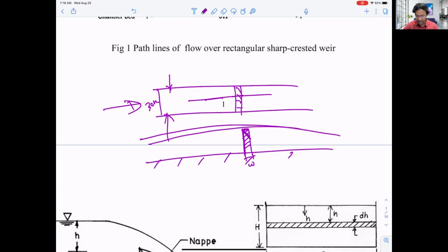How can we measure that? See, if water flows right over this, and if we can measure only this height above the weir, then we can calculate the actual discharge or flow rate. So that is our main purpose. It is so useful, right? If we just use one kind of dam, we don't have to use anything else. We have different types of weir as well. For this experiment, it will be a sharp-crested weir.